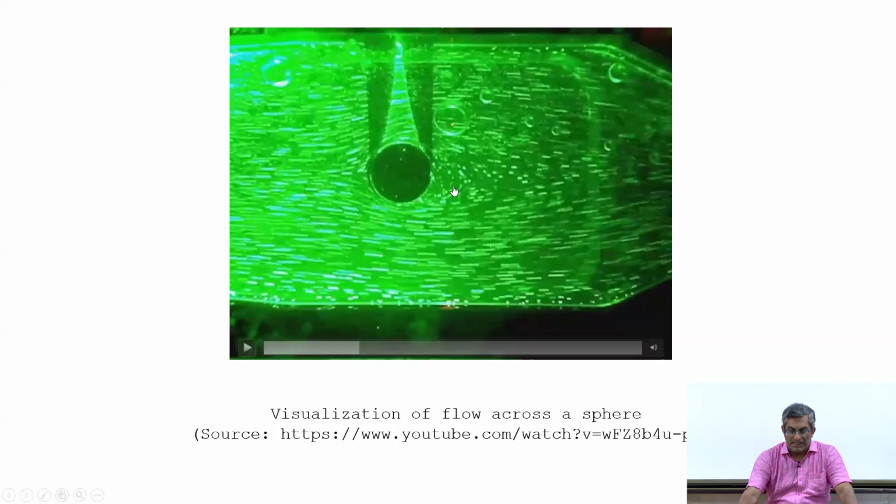But then why do we see particles here? This is because here the time scale of the flow is low, because this is in the wake region. Here, because of the boundary layer, the flow velocity has gone down. Whatever the flow velocity in the bulk fluid, it can be even supersonic flow, still, if you have a wall, the flow velocity there will be close to zero.